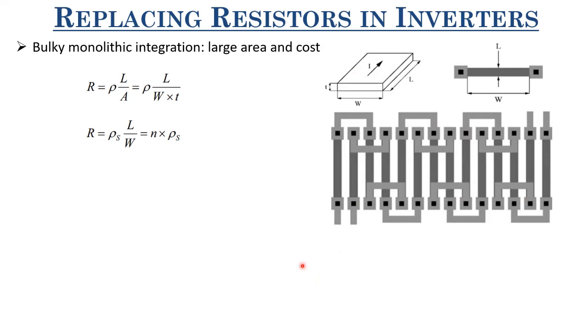Let's look at how we can implement MOSFETs as resistors. So we already know that in the linear regime, MOSFETs are voltage controlled resistors. Even in the saturation mode, they act like resistance. They basically act like a current source, but with an additional resistance, which comes because of channel length modulation, or because of that 1 plus lambda VDS parameter. So that is a huge resistance. And in the linear regime, you can actually realize different values of resistors using a MOSFET.